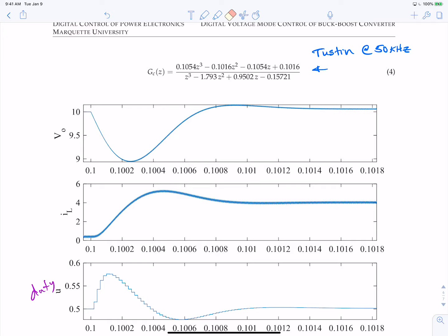Some issues would arise there too once you're trying to establish a bandwidth or a filter at 1 kilohertz while you're sampling at 200 times higher. The ratio between the bandwidth and the frequency at which you're sampling is quite high. Sometimes you run into accumulation problems there because you're accumulating over a lot of samples. You have to have a large accumulation size or bit size. So, for instance, 32 bits versus 16 bits.